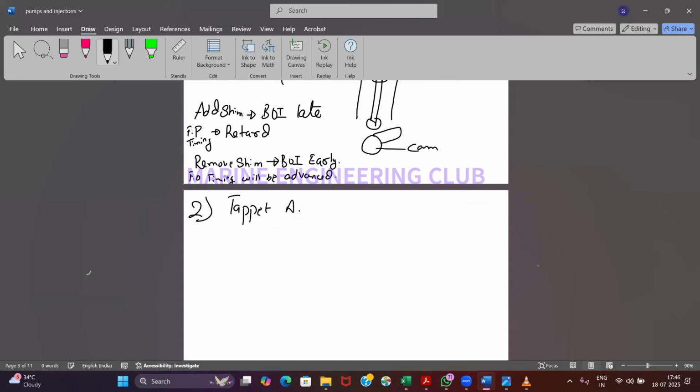तो सर ये जो शिम्स ऐड और रिमूव करेंगे तो ये भी सर बीओआई को देखते हुए ही करना है क्या सर? Yes, आपको पहले टाइमिंग लेना है ना. Okay, first you will take timing and accordingly you will check with your manual if the timing is correct or not. If it is early and late, then with respect to that you have to add or remove the shims to make it correct.